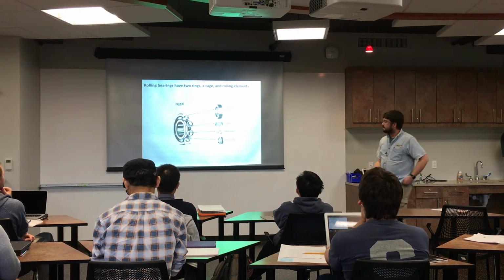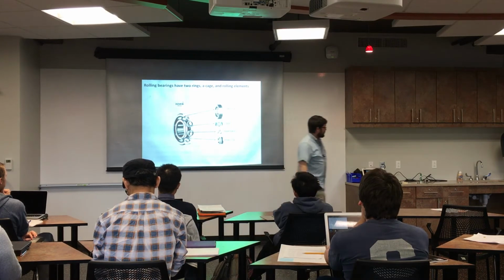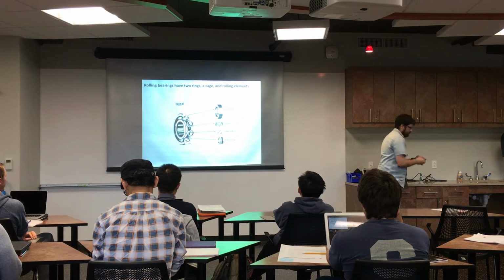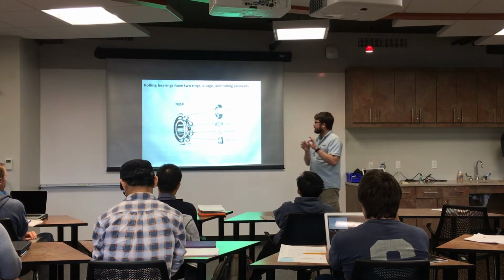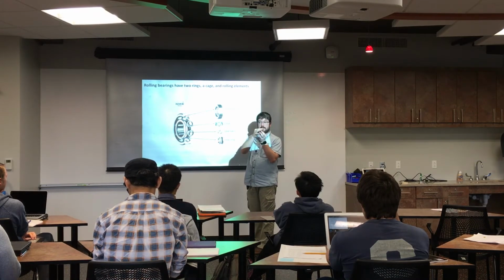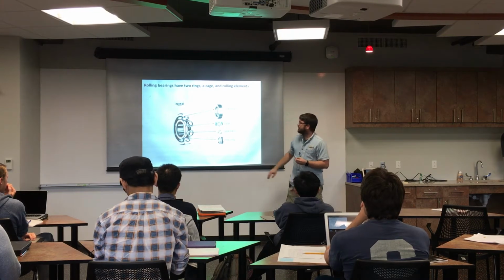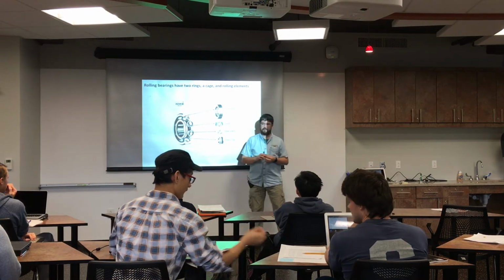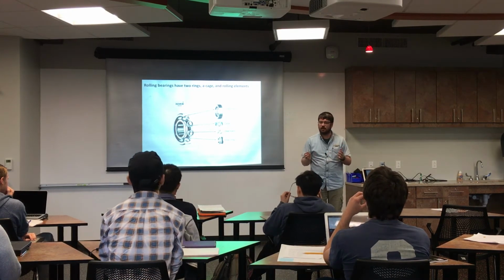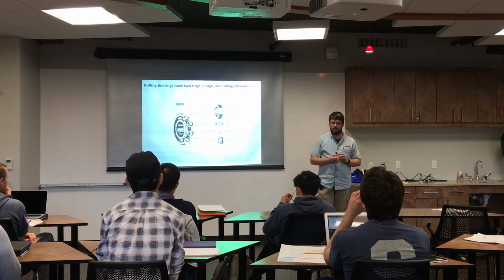And here's the cutaway version of that. You've got the outer ring, which is what you're holding on to when you grab it. And you've got the inner ring, the balls and the cage, which you can see part of as that split material coming out the side. You'll also hear the inner and outer rings referred to as the bearing races. That's another term you'll commonly hear: people say that the races of the bearing are worn. It just means that those are worn out and the bearing needs to be replaced.